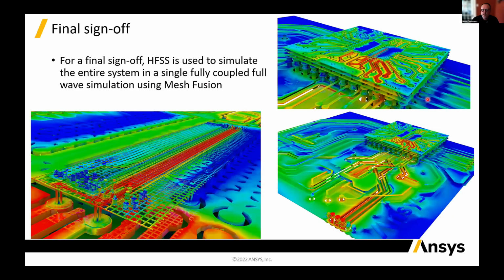Next slide. So lastly, with this combination of the very performant on-chip extraction tool, RaptorX, you can design the IC-based part of your design very quickly, brought together within the HFSS 3D layout workflow. Again, as mentioned earlier, the RaptorX engine and the HFSS engine are coupled through a technology called HFSS layout components. These can be stacked together, built up in a system, and allow you to do a final system sign-off with a combination of optimization and HFSS solutions.